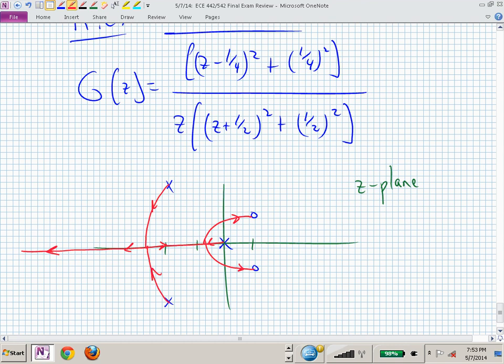If you find the departure angle is, let's say, 260 degrees, that's consistent with this, isn't it? Now, what's another check? And then you could say, oh, my arrival angle is 190 degrees. I'm coming in at 190 degrees, right? Well, that's consistent with this.